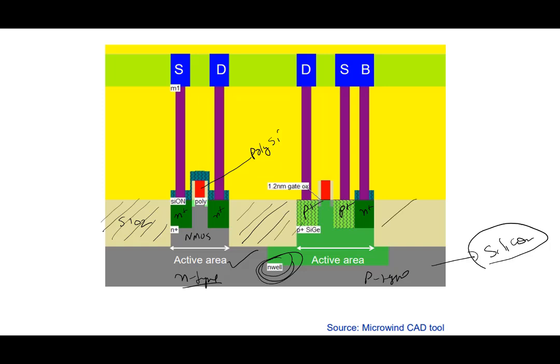Okay. And there are different kinds of silicon dioxide deposited using different methods. So this is also silicon dioxide. And the first layer of metal is over here. This is called metal 1. First layer of metal, right? So with the first layer of metal, if you were making a CMOS inverter, for example, you would connect these two together. So on top you would do all that here.